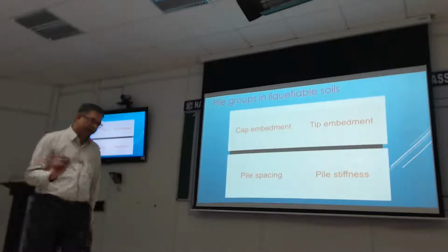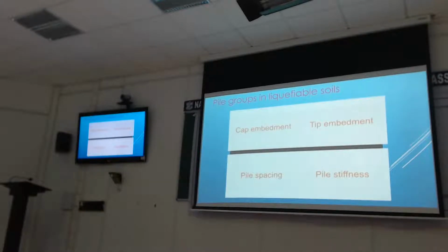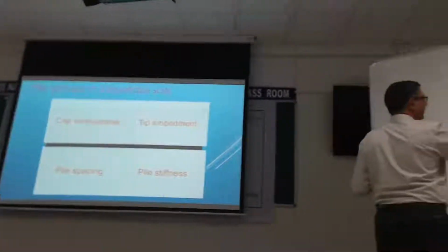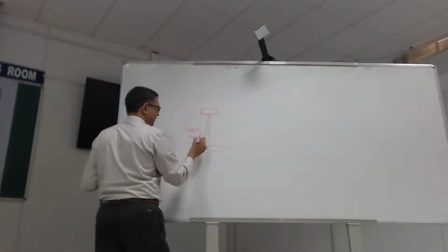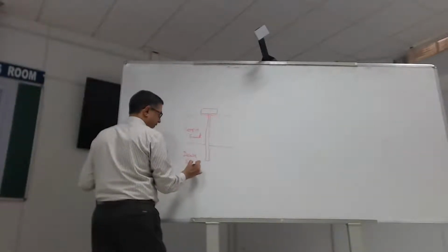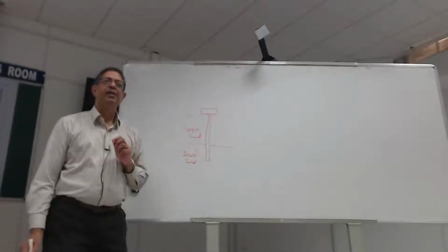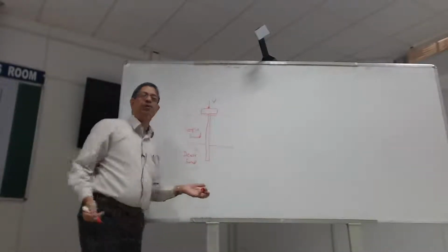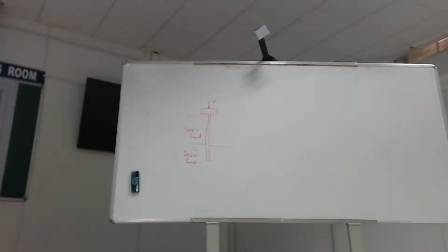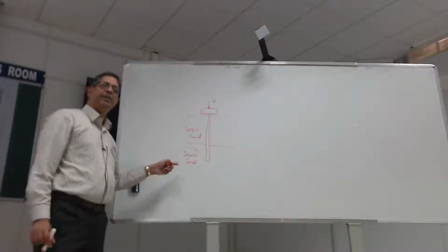But one point I wanted to impress: we talked about pile buckling, right? Now, the real research question you're going to ask is, if I have a pile, and that's my say weak layer, a loose sand or silt, and this is dense sand, okay? What we haven't considered is, if I have my normal vertical load, is it easy for the pile to buckle or to settle into the slab? And there is some evidence and reason for this.